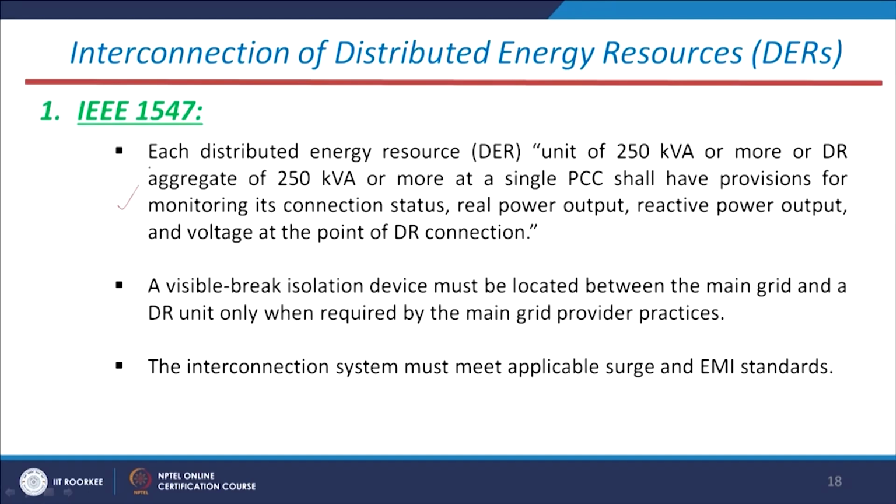Another standard, a rule you can say, is that each distributed energy resource or DER unit of 250 kVA or more, or a DER aggregate of 250 kVA or more at a single PCC, shall have provisions for monitoring its connection status, real power output, reactive power output, and voltage at the DER connection.